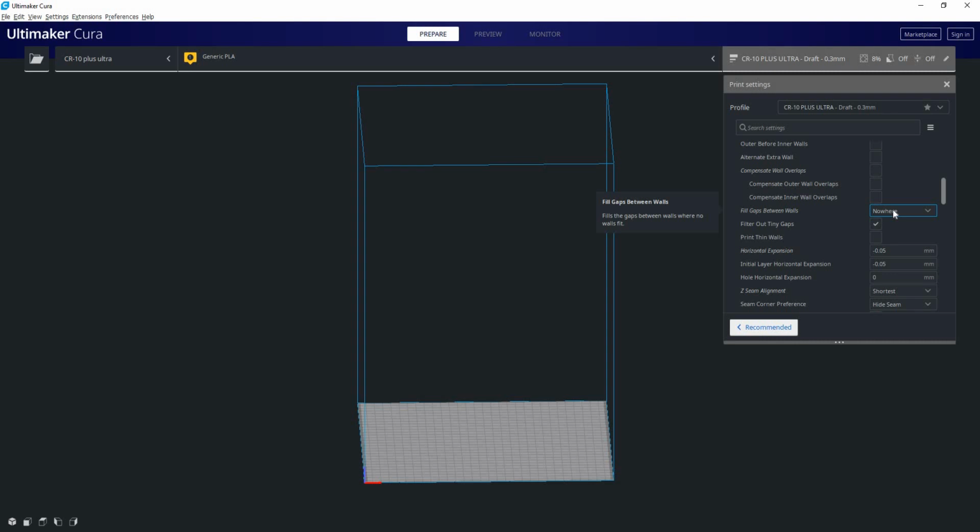So a 3.2 millimeter thick wall printed with a 0.5 millimeter line width is going to leave a 0.2 millimeter gap in there. And that's something you want to try and avoid. Instead of making that wall 3.2 millimeters, if you had made it exactly 3 millimeters with a 0.5 millimeter line width, that perfectly divides in, meaning there will be no gap between those walls. So the best you can do, if you did not design the model, you cannot adjust those dimensions. So in that case, your options are adjust your line width to produce a value that fits within that dimension, or you can use the next setting here, which is our horizontal expansion.